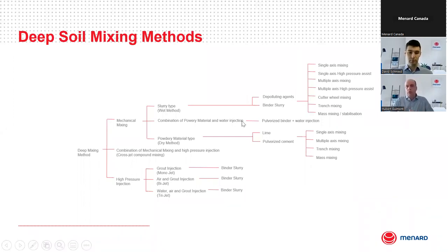It's important to notice that you can do either wet soil mixing or dry soil mixing or high pressure injection. We've put here the jet grouting into soil mixing. It's partially soil mixing. Let's say it's almost soil replacement, but sometimes it could fall into the soil mixing type of application.